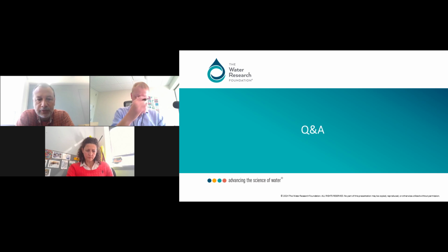That wasn't that good in retrospect because we got to solids concentrations that the sludge wouldn't settle. So the SVI seems to be a bigger thing. I think the industry has now different ways of dealing with poor settleability sludge and additional things that could be tested. But that's more of a physical phenomenon, in my opinion, that will need to be tested or answered in a different way.